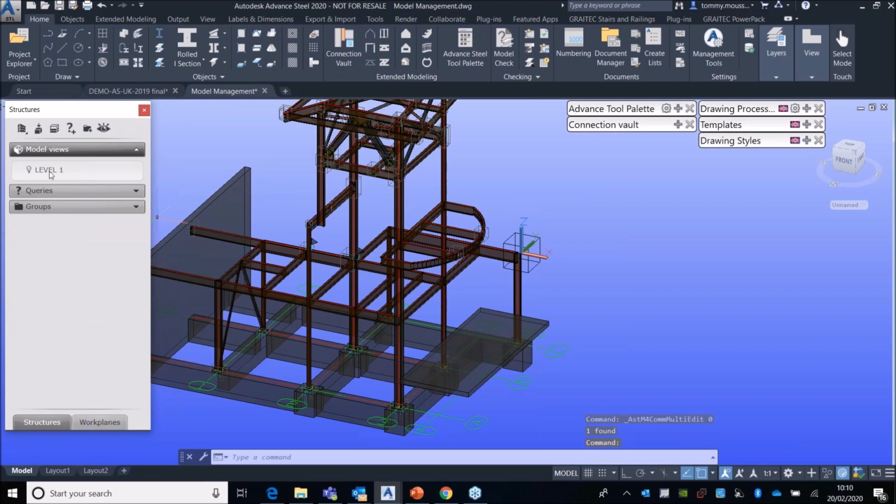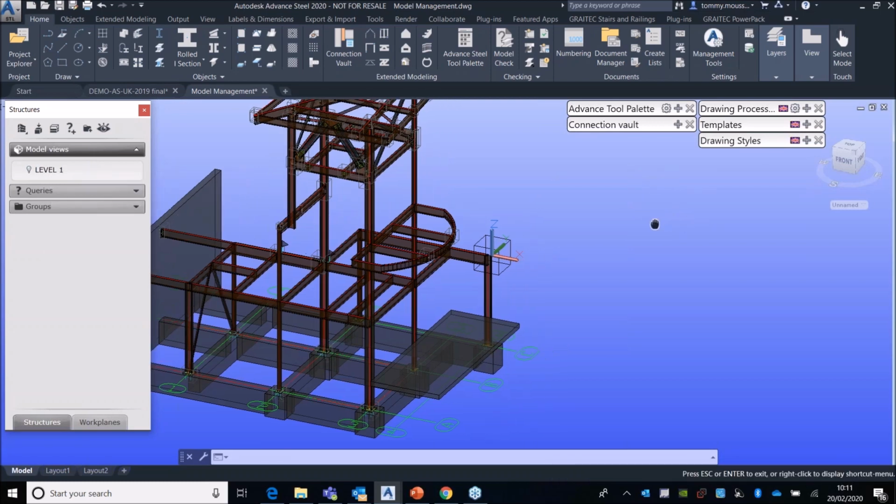And that's an example of creating a level with 1 point at UCS. Now here you do have some options if you were to right click on level 1 within the model view. So here, of course, you can turn it on, off, you can erase, you can rename it, you can check it out and have a partial checkout. Those things I'll go over later on.